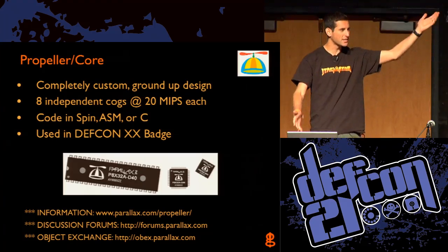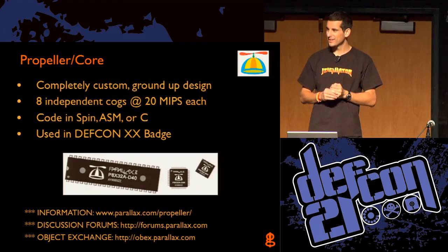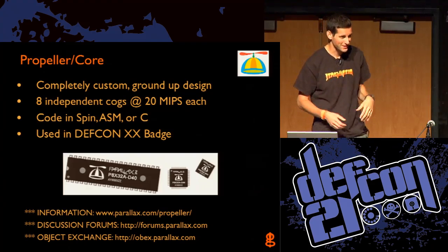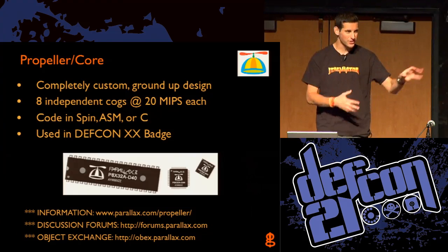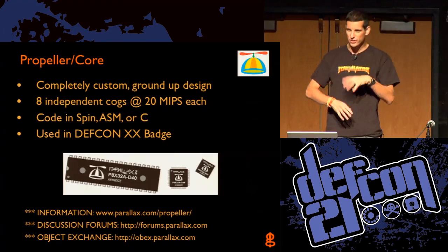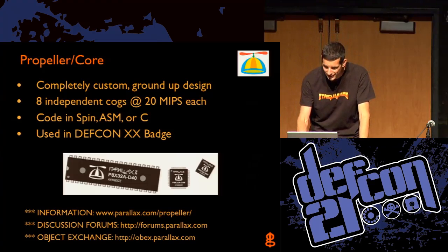If you guys were here last year, Defcon 20, right? You guys have Defcon 20 badges? Yeah, okay. Those are all Propeller processors. So in theory, you could load the JTAGulator code onto your badge and connect up to stuff, but you don't have the input protection and target voltage settings, but you could if you wanted to.